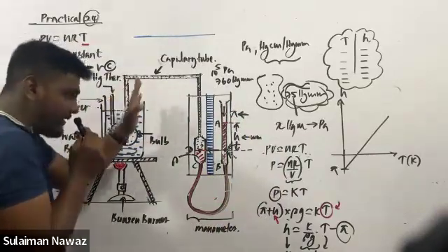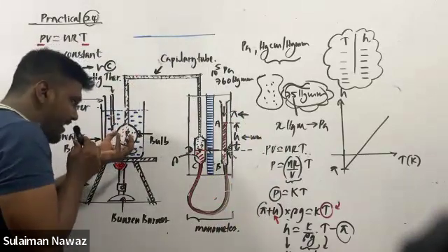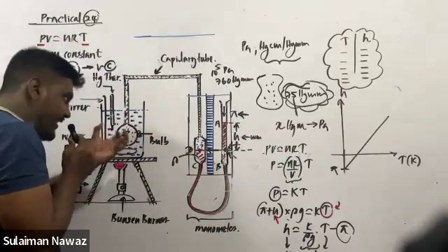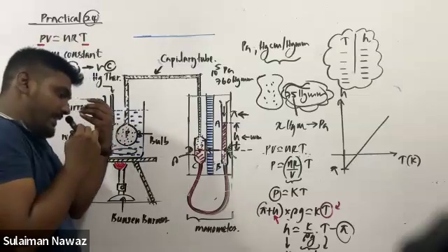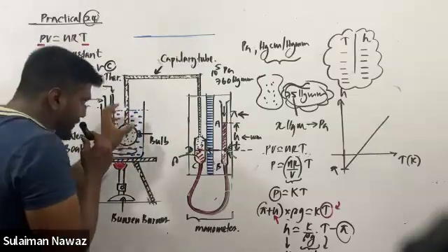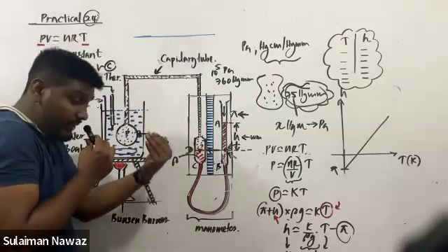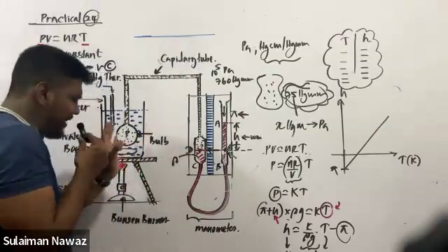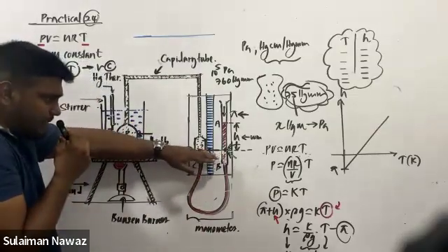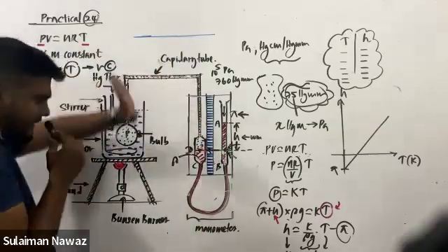The capillary tube's expansion is not considerable compared with the bulb's, but the bulb is actually expanding. So in the real scenario, we can't consider the volume of the gas inside the bulb constant. If you neglect the expansion, then we can say that if you maintain the mercury level at the same indicator tip level, the volume of the gas in the bulb is the same.